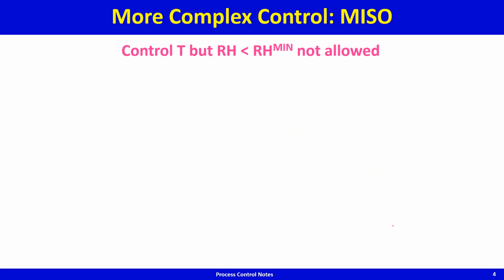Now let us say on a particularly cold day, winter air is very dry. If you have a particularly cold day and you have your heater giving you 25 degrees Celsius, then what will happen is, because the dry air has been heated and no water has been added to it, the water content of the air remains the same, but hotter air can hold more moisture, so the relative humidity goes down and the air will become extremely dry, and in such extremely dry air conditions you can get things like nosebleeds, which can be very uncomfortable. So the whole idea of the heater and the control system is to have a room that is comfortable for the user, and here on a particularly dry winter day, the heating is actually creating a discomfort due to the extremely low relative humidity.